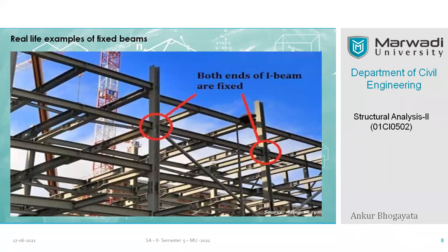And that is why it is called a moment resisting frame or moment resisting structure. So if all the beams are rigidly connected with all the columns, that entire structure, entire setup or frame is known as a moment resisting frame. But please keep in mind that not all frames qualify as 100% moment resisting frames. That is a separate point, and don't worry about it much. I just wanted to give you a glimpse, because moment resisting frame is not a point of our interest right now. I just wanted to give you a reference.